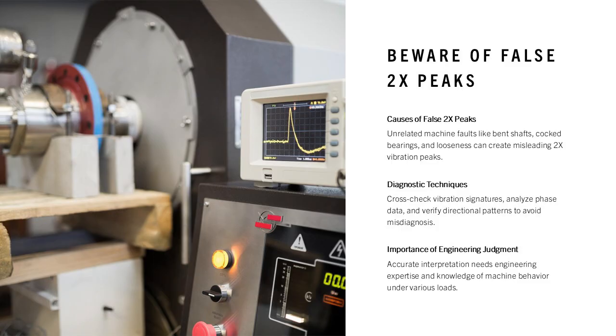A critical diagnostic challenge is that several unrelated conditions can also produce 2 orders running speed vibration peaks, leading to misdiagnosis. These include bent shafts, cocked bearings, looseness, resonance interactions, and eccentric components. This slide emphasizes cross-checking vibration signatures, analyzing phase data, and verifying directional patterns to prevent false conclusions. Proper interpretation requires engineering judgment and experience with typical machine behavior across load conditions.